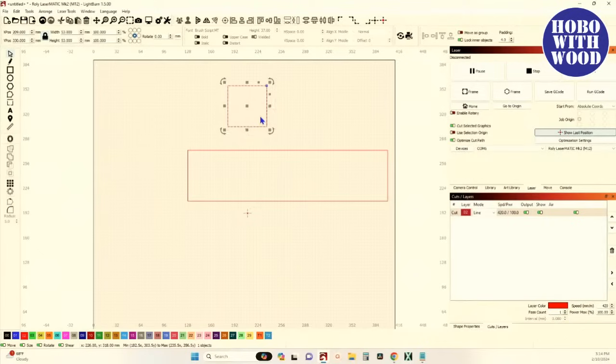But if you hold the Alt button while you're dragging this square around, as you get close, a guideline will pop up. It tells you you've got your left justification lined up. You can take it out here to the outside. Now it's going to do left and right justification to those two pieces. And as you bring it down to the corner, you get another guideline that pops up that tells you you're justified with that top row on that rectangle.